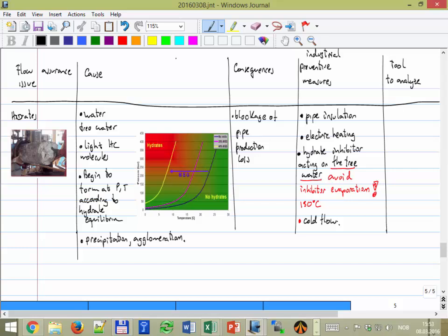and that's where the problem causes. So some people go to the approach that they say we're going to induce hydrates, but we are going to avoid agglomeration, and we are going to transport it in some kind of a slurry. A bunch of solid particles of hydrate, just like a slushy, like this thing that you drink in summer when you are thirsty and you want a refreshing drink. You have particles of hydrates mixed in the flow, okay. But the question is how then you avoid that they agglomerate.